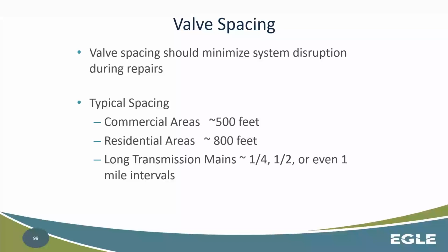The general rule of thumb: if you have an intersection where the water main is going in four different directions, north, east, south, and west, let's say, you should at least have the number of valves that's one less than the number of connections. So if there are four connections there, you should have at least three valves, because that will give you the opportunity to isolate any given main that's necessary, whether that's closing all three valves or just closing one to isolate that portion. Again, minimizing disruption to the community, and potentially isolating an issue as well.